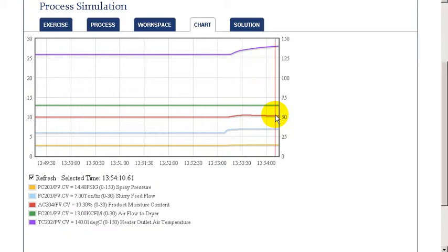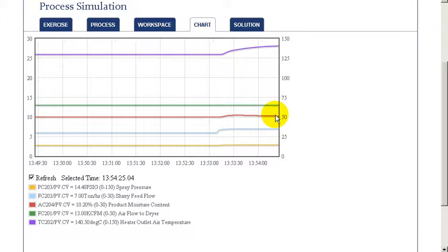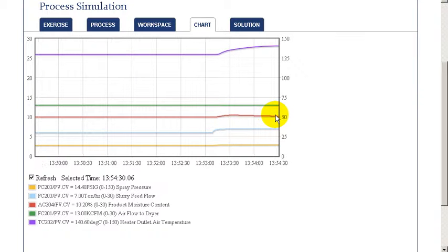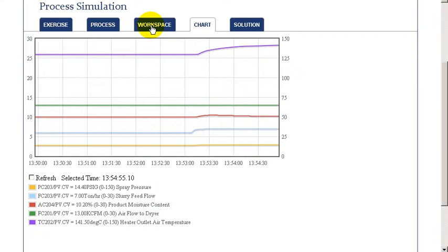That in turn caused the composition control to change the outlet temperature target, and so that's being automatically adjusted. So the change in slurry flow increased the product moisture. That is, it was a wetter product, and it requires now a greater temperature to dry the product.